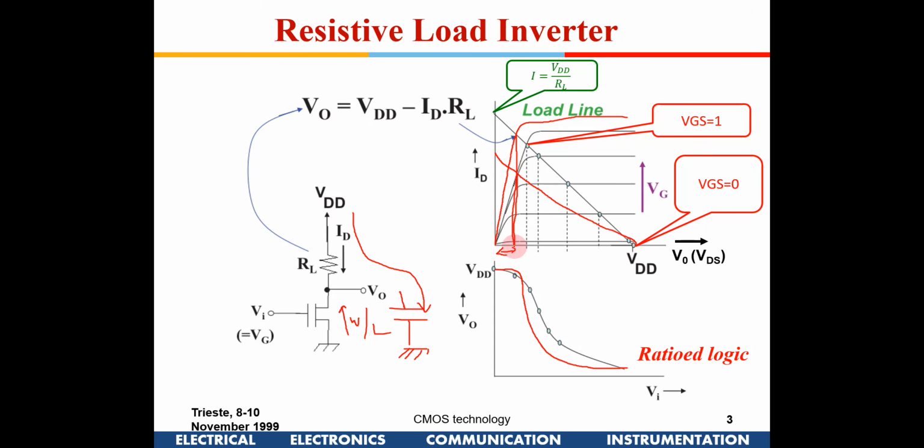Now can somebody say what would be the drawback of increasing W by L? Capacitance, so the delay. Pardon? Capacitance and the delay. Delay won't be affected, because this is where it is going to charge. In fact, it is going to improve this path delay, right? It will be able to discharge this, so my fall time will improve. Can we think of some other disadvantage?